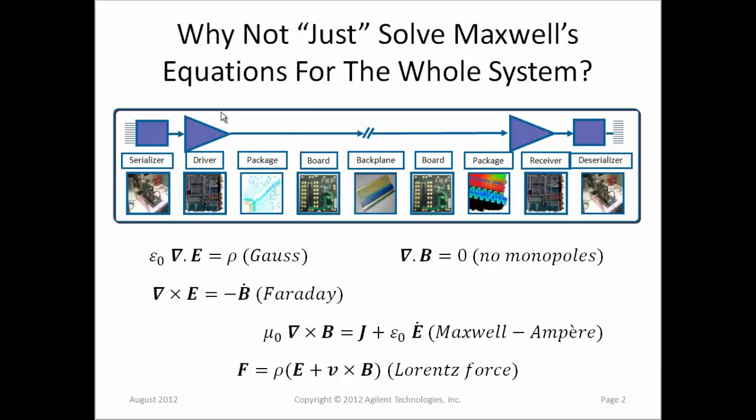So S-parameter models help solve both of these problems by abstracting the behavior of a particular component away from its implementation, and it does this in a way that is both computationally efficient and also hides the intellectual property of the component vendor.